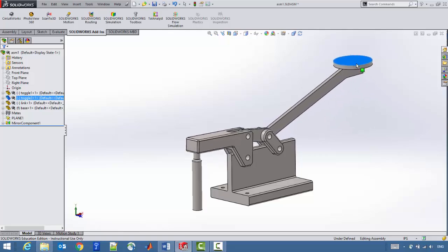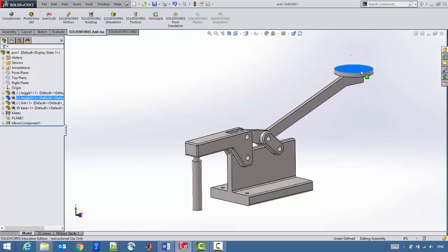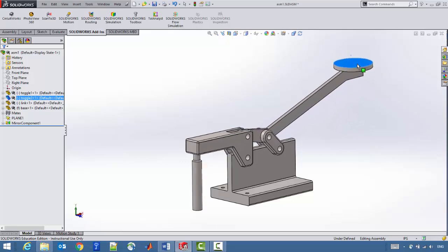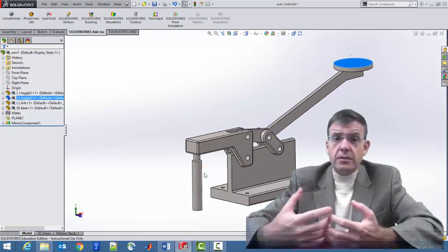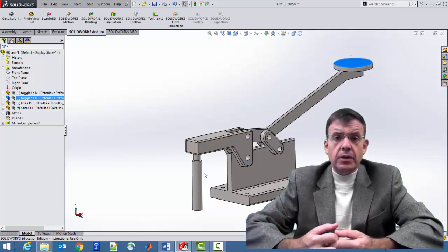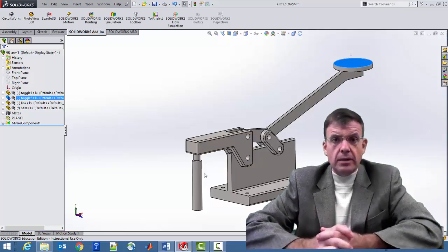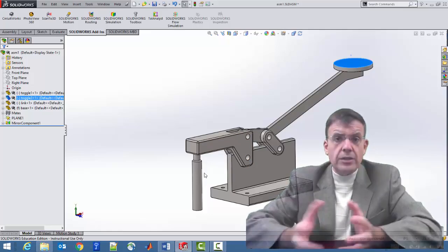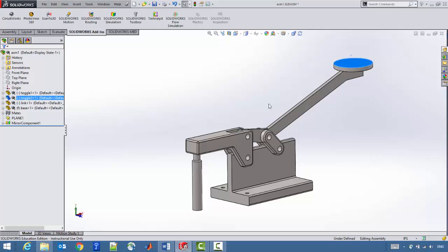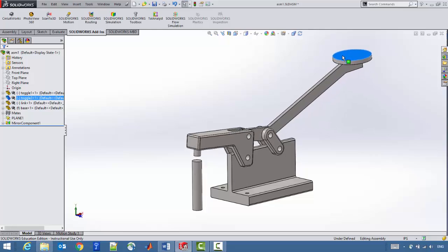Now, there's no way with the mates other than distance mates to give awareness to the clamp that there's interference about to happen between the components at the mate level, at the assembly creation level. But this is something that we can in fact do at the motion analysis level. And this is when you have the highest level of simulation capability for rigid body mechanics, which is to say, again, motion analysis versus basic motion or animation.